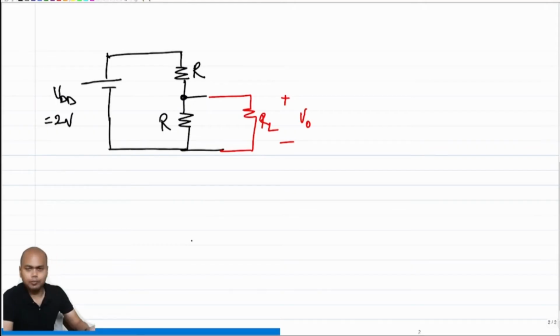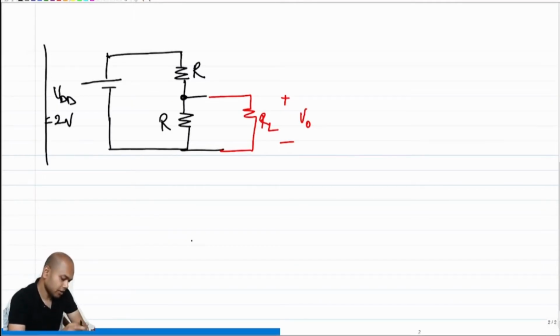So we did this from the perspective of output resistance, and I hope you have also done it from the perspective of figuring out the total resistance or the total V0, right? And then I'm sure we came to the same conclusion. Now, the curious among you might also have gotten a third way of looking at it, and let me spend a couple of minutes on that third way. The third way is that if I use Thevenin's theorem, or rather Thevenize this circuit in the box,